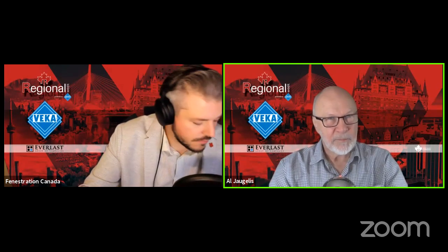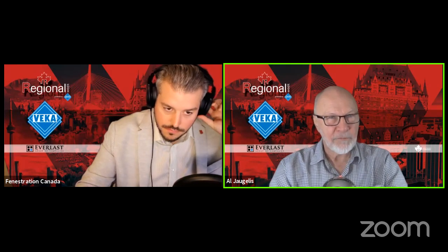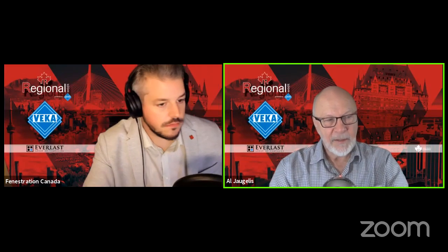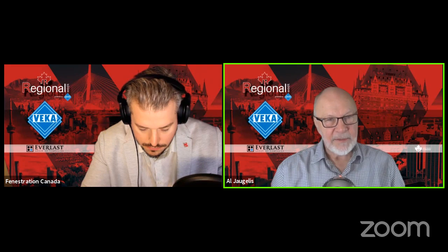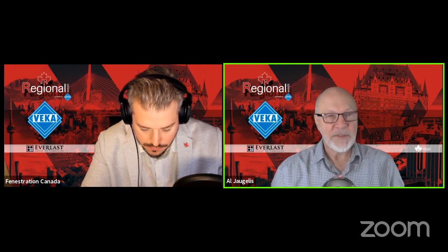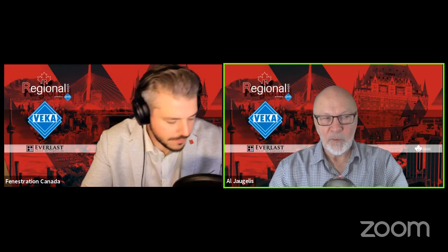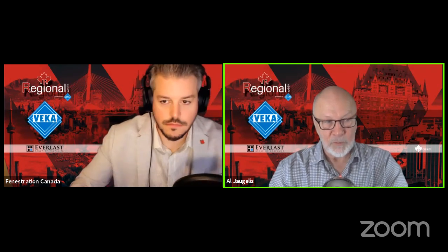Interestingly enough, though, I haven't looked at this in the national code, the fire resistance. In the BC building code, the BC building code didn't adopt the language in NBC 2015. They did something similar before the national code did. And the way they did it, they did exempt the products that had a fire resistance rating from NAFS testing. So the BC code did have language related to fire resistance ratings as exemptions to NAFS. I didn't see those in Part 5 of the national code.